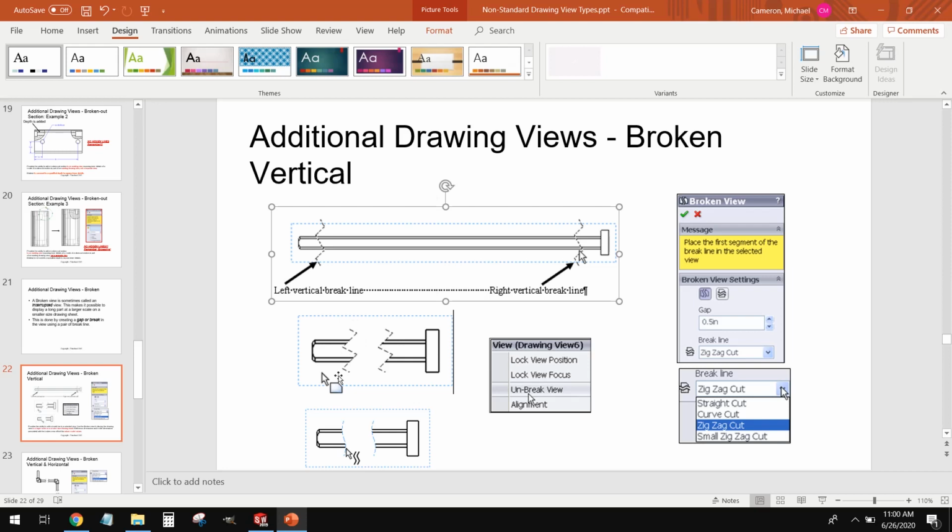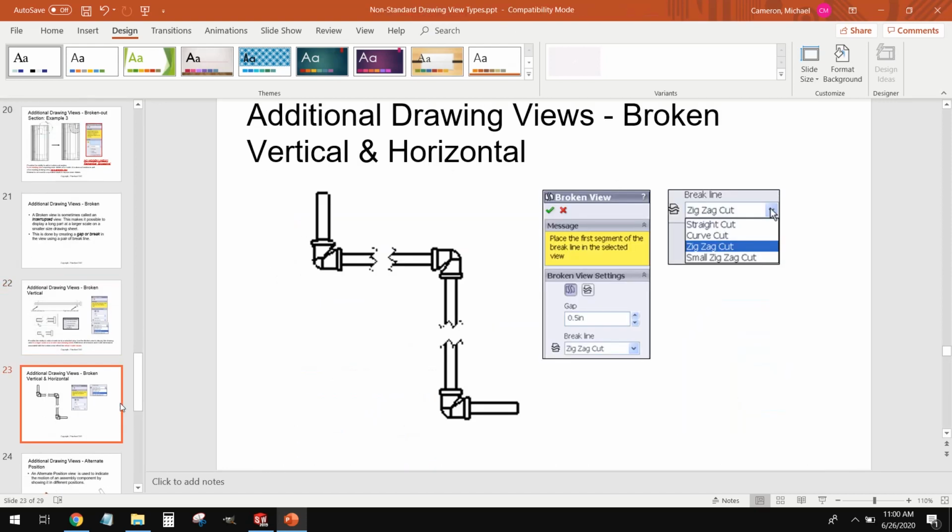And when we see this on a drawing, we know that this is indicative of a longer part, but it's all the same. So what we do is we truncate this to shorten it up to fit on a standard drawing. You'll especially see this with plumbing drawings, right? If this was an 8-foot section here and a 1-foot section here, our drawing would be really uncohesive.